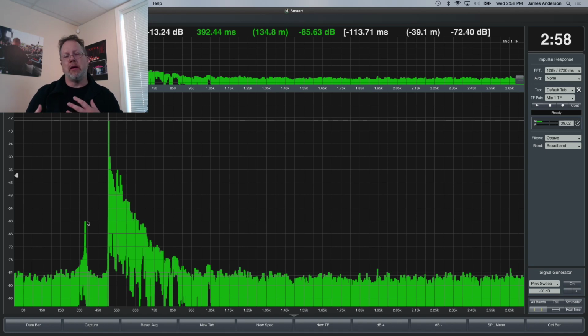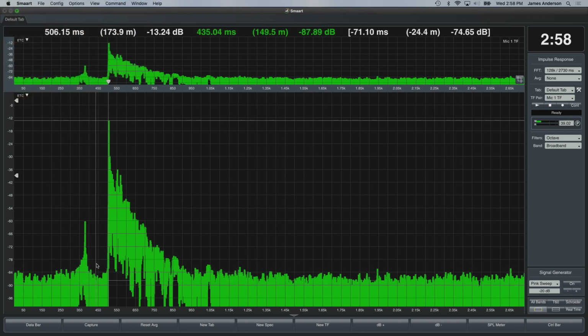But in my measurements, I need to account for what's going on acoustically in the room. I need to be able to account for its impact on tonality. Same thing with harmonic distortion, its impact on tonality and transmission quality or intelligibility. Tonality is in the magnitude trace, timing is in the phase trace, and transmission quality is in the coherence trace. So there's my sweep sine, but this measurement is really nice for being able to separate out linear and nonlinear components of the arrival.